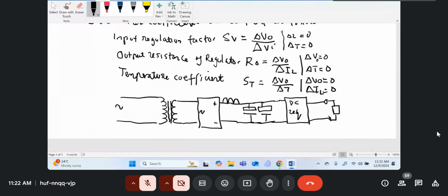So for Kenya Power, where I stay it's normally around 230 volts. If the input is 230 and the output is say 40 volts, and then the input increases to 240, the output will increase with the ratio of 40 times 240 over 230. That will be your AC voltage, because here the 40 volts is still AC, and it is rectified and smoothened with capacitors.